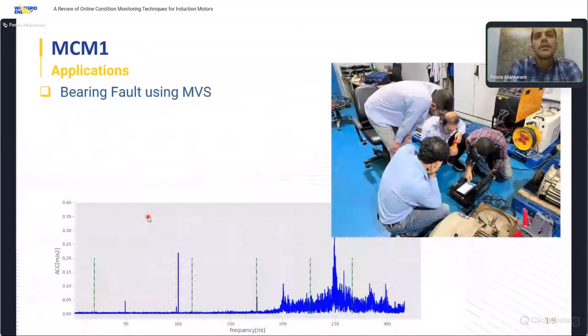Here you can see the bearing damage of the electric motor, using the vibration measurement with the MCM1 device. It is important to understand that bearing failure usually develops in multiple stages. Often the first sign of trouble is caused by improper lubrication. If this issue is not addressed early or is left unchecked, the fault will progress over time and get worse. It can also affect other motor components such as the bearing housing or other parts of the motor like the shaft of the rotor.